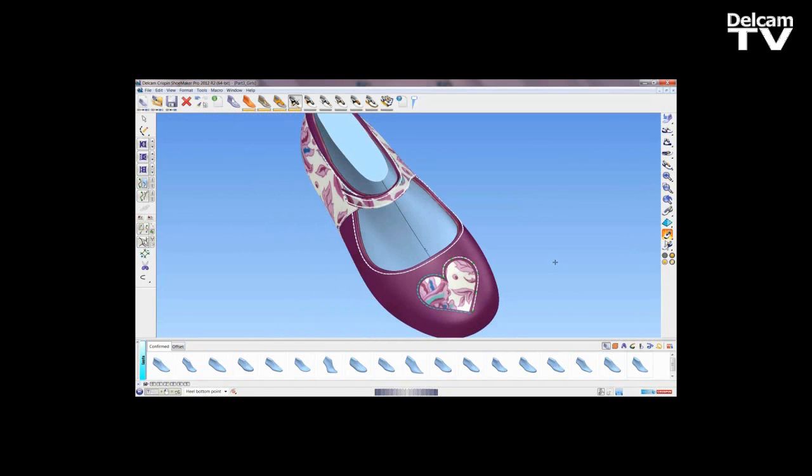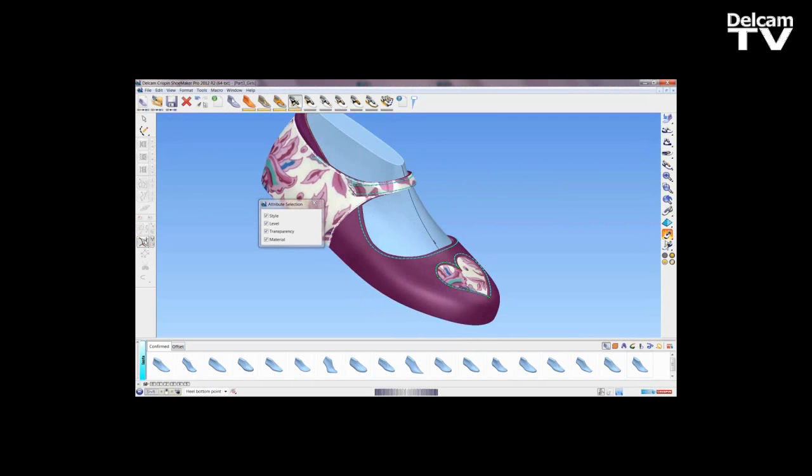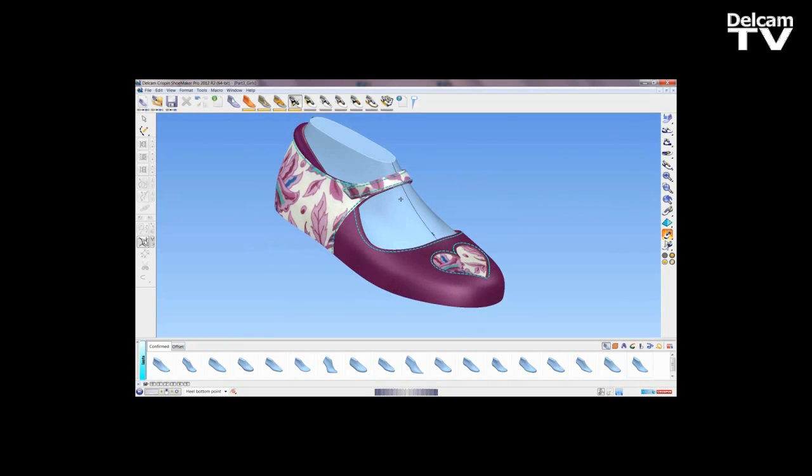Once edited, we can change the colour and style of the stitches. To do this, we're going to use the Paste Attributes button. So simply select the first pre-drawn stitches and then use the Paste Attributes. Make sure all of the attributes are turned on and then select each of the lines. Hover over the lines until they're grey and then click on them. Right click to exit the mode and the stitching is complete.